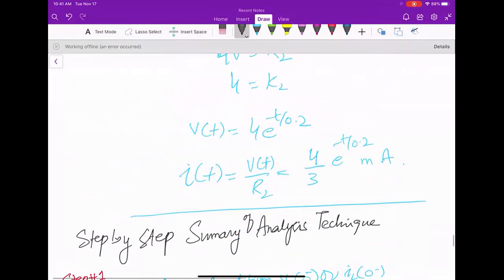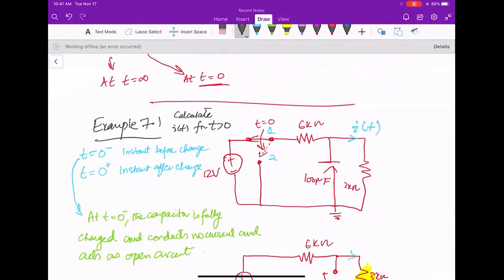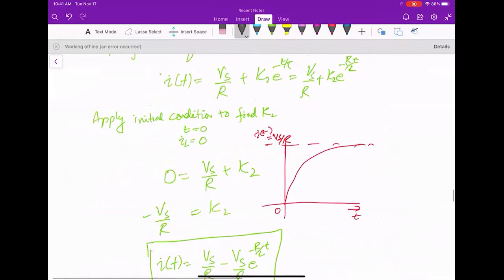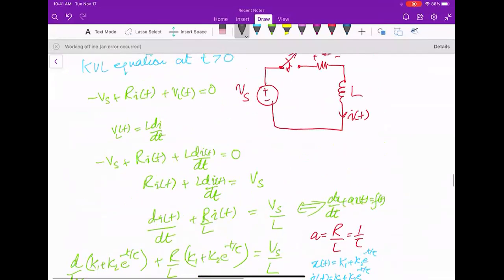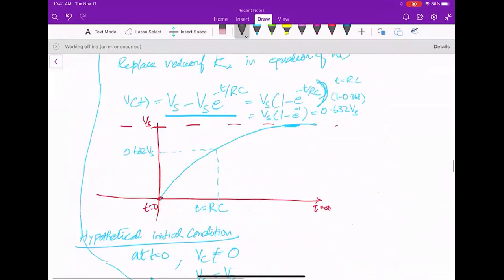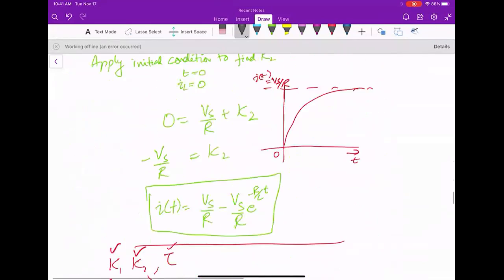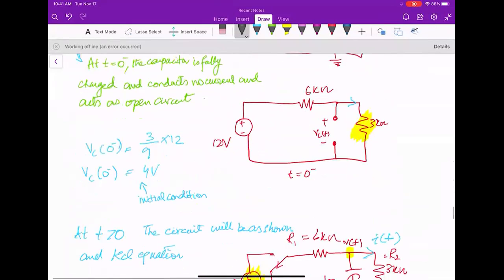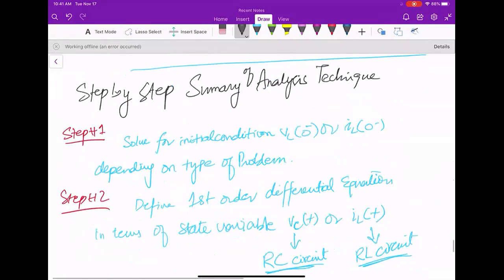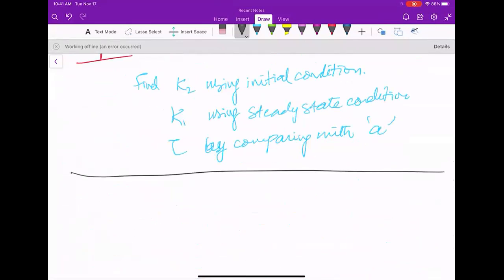One thing you have learned maybe in calculus is that the first order circuit is the circuit in which you have a linear equation or a first order differential equation, right? That's what you have learned. But in circuits, first order circuit is not only that in which you have a first order differential equation, but the first order circuit is in which you have one storage element, like either you have a capacitor or you have an inductor.